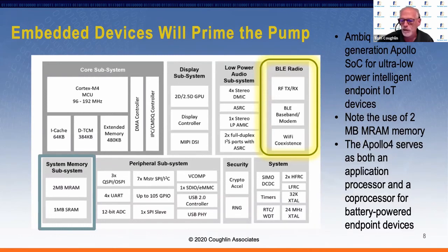Their need for a NOR replacement has already driven major foundries, TSMC, Samsung, GlobalFoundries, and others, to develop emerging memory technologies, mainly MRAM and resistive RAM, to replace a stalled NOR flash technology. In addition, MRAM is much smaller than SRAM, allowing more memory using MRAM than SRAM on a given size die.